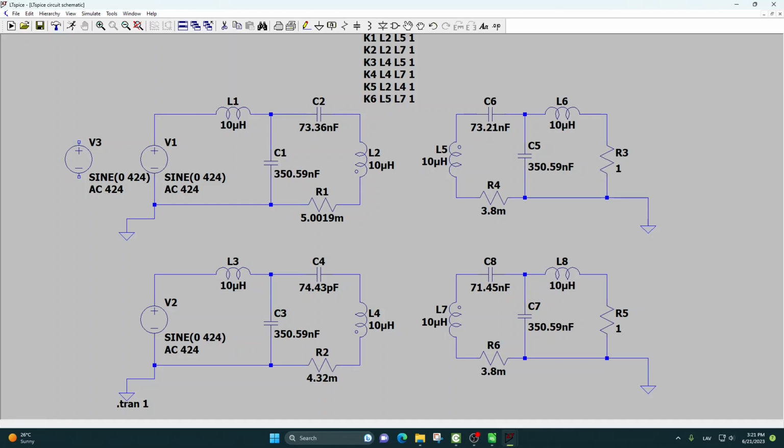This is a must. If you have a DC source defined within your LTspice simulation, for example if you have an inverter schematic, simply replace it with a voltage source, because this is currently the only source type that works.